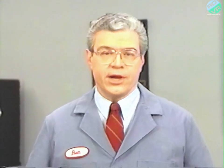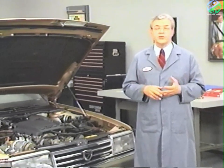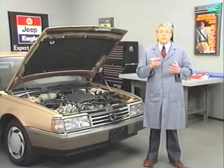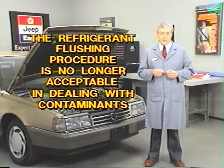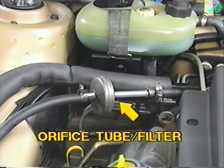Now, before we conclude our AC tips, there are two more items we need to discuss briefly. The first is concern with orifice tube replacement due to system contamination. Now, in the past, when servicing an AC system that had been contaminated by, say, compressor debris, you would have had to flush the system with large amounts of refrigerant to make sure that a new orifice tube would not be plugged. With an increased emphasis on sound environmental practices during AC service, the flushing procedure is no longer an acceptable way to deal with contaminants. As a result, Chrysler has now made available an orifice tube which is part of an inline filter and which eliminates the need for system flushing.